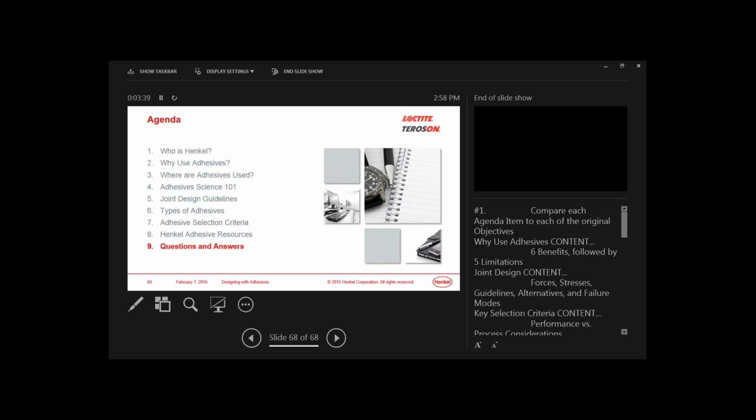For your particular application, given your requirements for not only the good appearance, but the ability to shape and sand and kind of machine the adhesive surface, I would use our E30CL epoxy. Oftentimes our light cure acrylic urethanes are somewhat soft, and they don't respond too well to abrasion. You know, they get kind of dull, so to speak. So I would normally recommend our Hisco E30CL clear epoxy, which is an exceptional candidate for bonding glass. It has a long open time, long working life of about 30 minutes. It should work very well for your application.